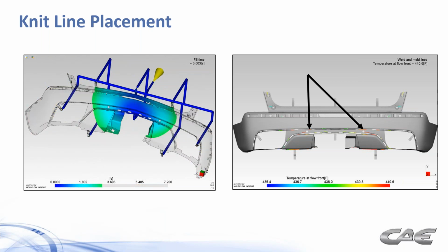But my best advice is to stay away from high pressures as best you can, and use MoldFlow to do it. Stay 5, 7, 8,000 psi below your machine's limit, and you should have enough to account for the other pressure drops that MoldFlow is not directly accounting for.